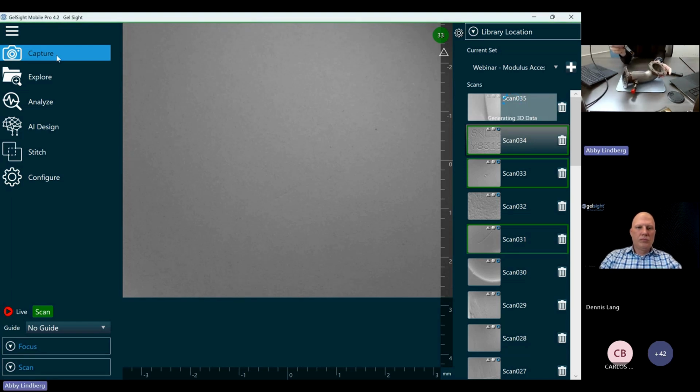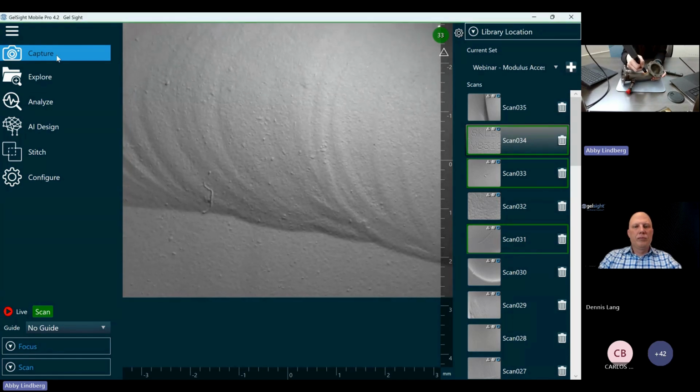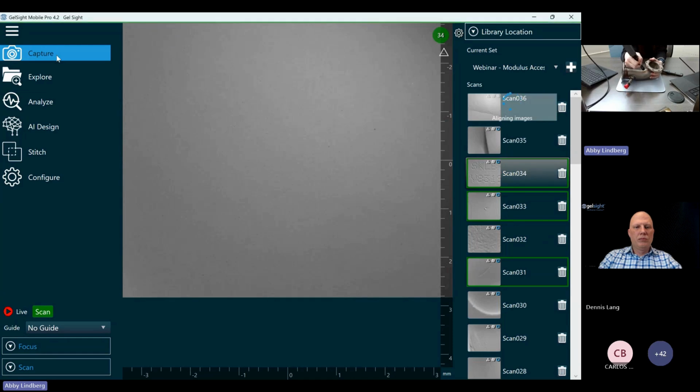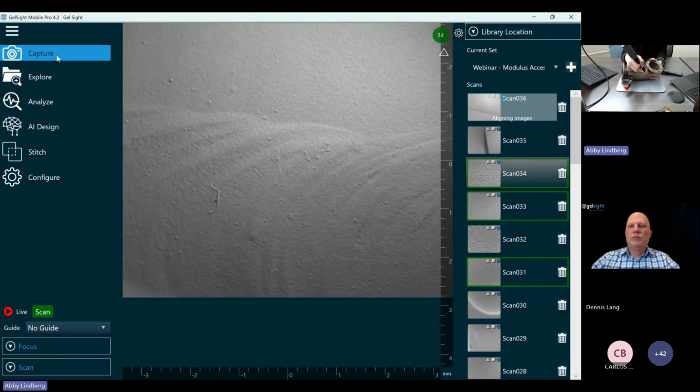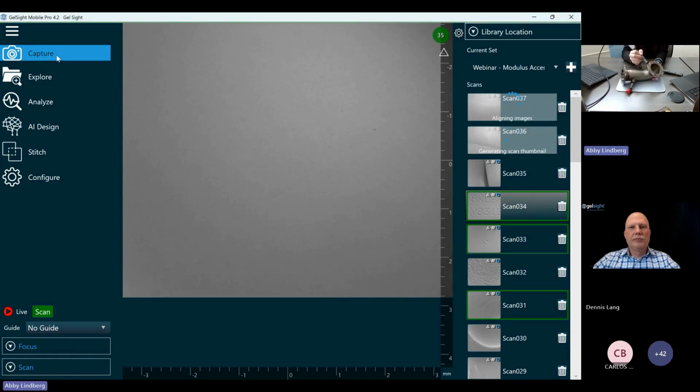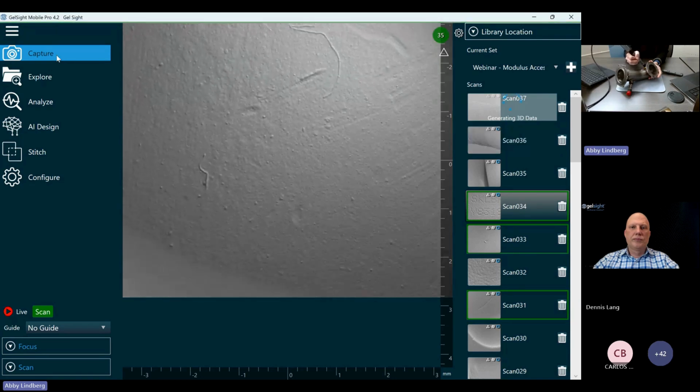Additionally, we could turn this around and get access into this area with this weld. Maybe we were looking at some defect along this weld, or an undercut or something else. We could have access here. Or even along this interface here, where we also wouldn't have had access before without replica material. I'm going to press onto that surface.